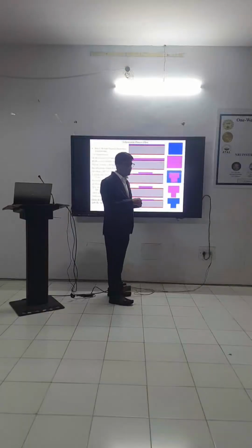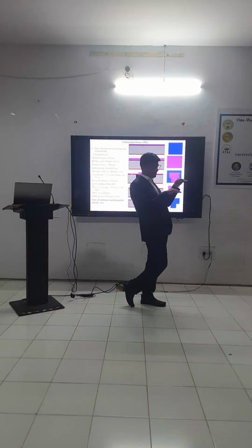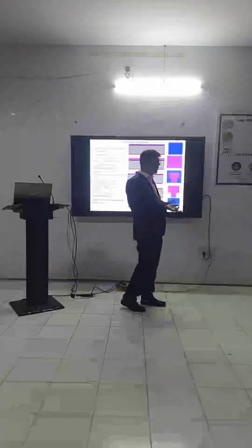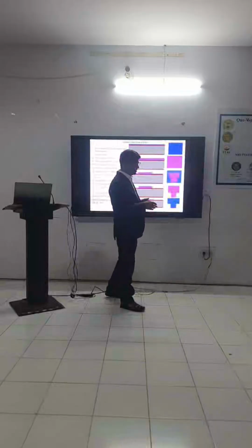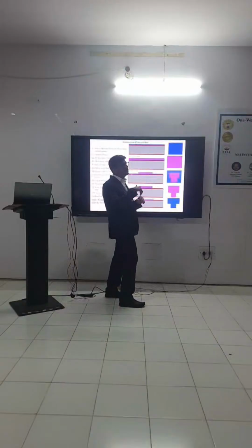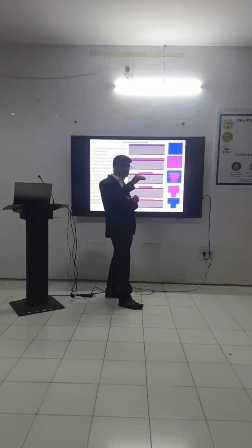Why do I require three mirror layers? Because if you have a very high acoustic impedance ratio, you can achieve it with two reflector layers also. Clear? So for the reflector we do not require any lithography, but the number of steps increases for your deposition of metal or oxide. So it will increase your number of deposition steps, not lithography steps.